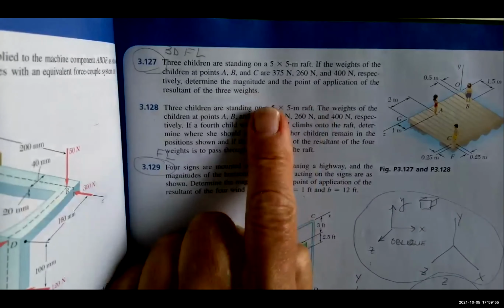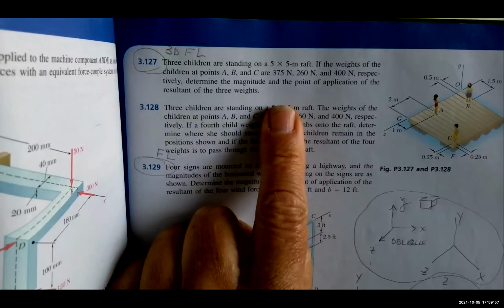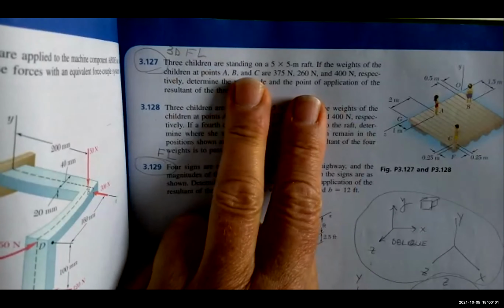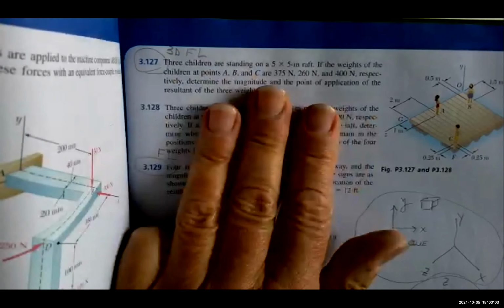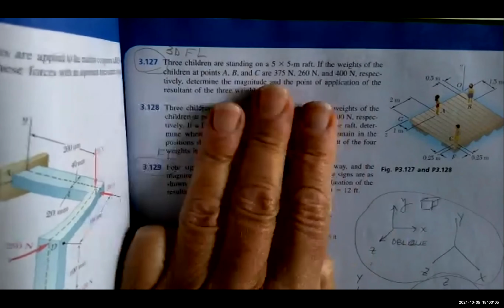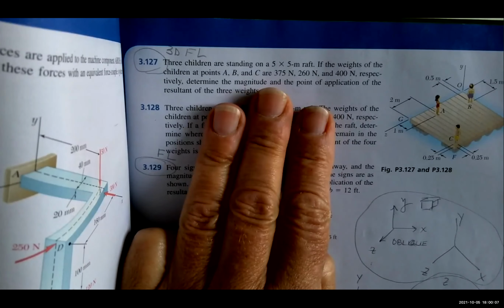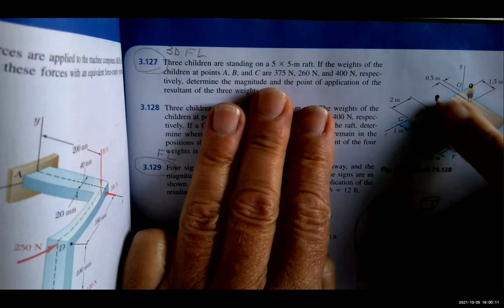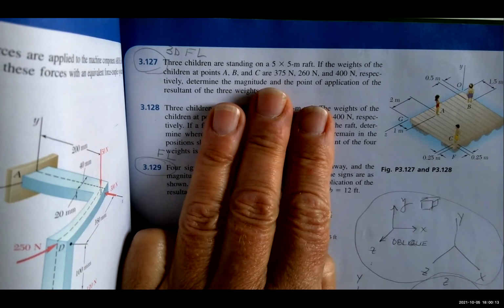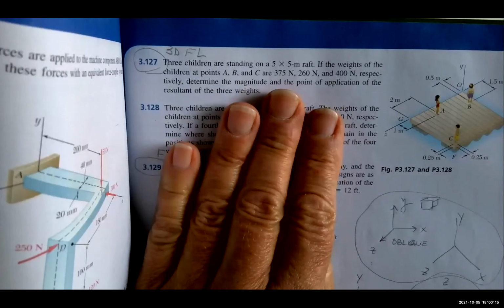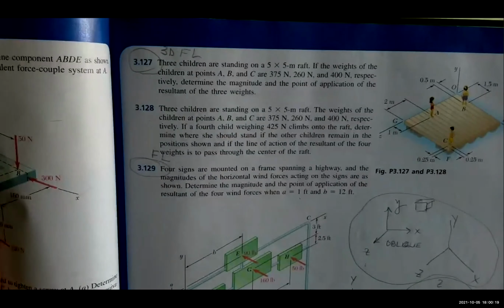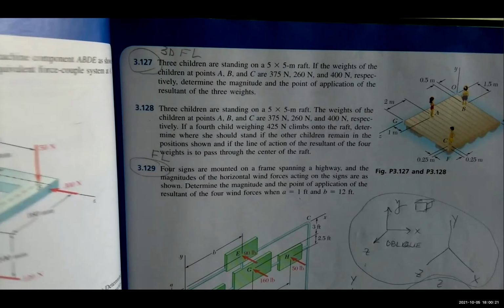Step 1, you find the resultant force. And then you find the resultant moment. And then third step, solve for the perpendicular distance. And it's 3D, so you're going to have 2 distances. And then 4 is? You draw it. Yeah. Great. Draw the one force, the resultant force at the distance.